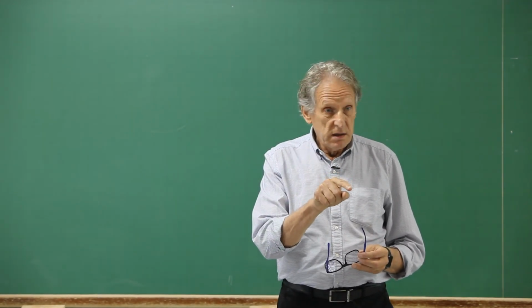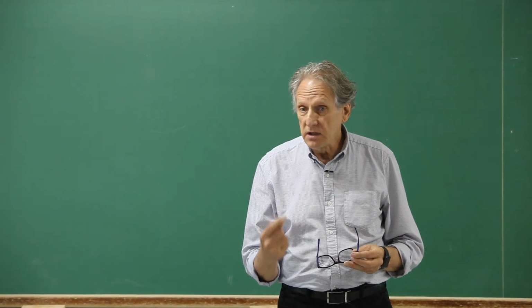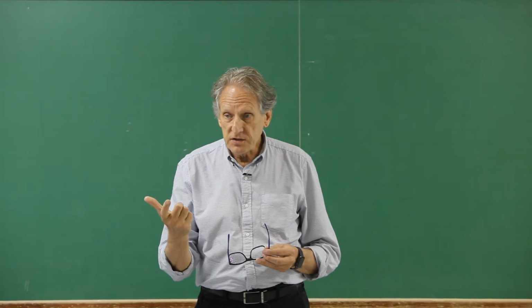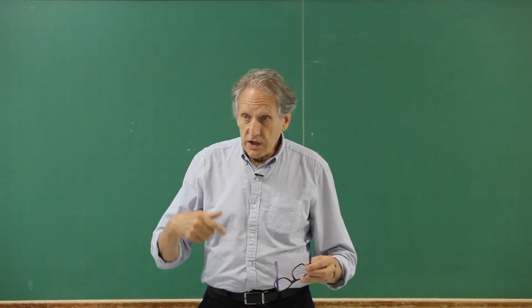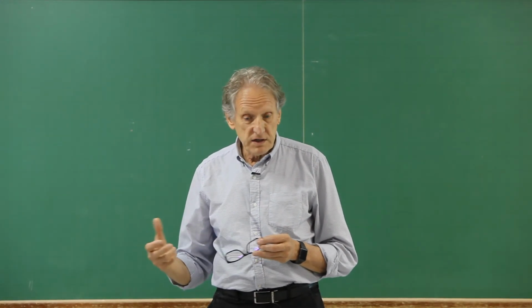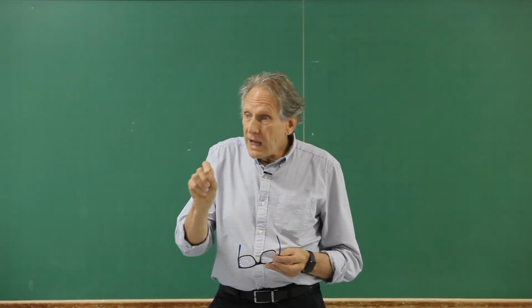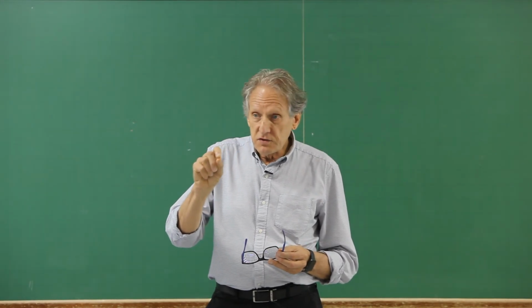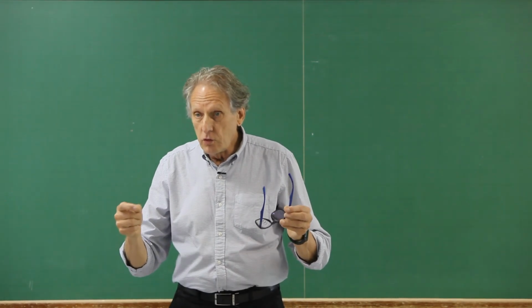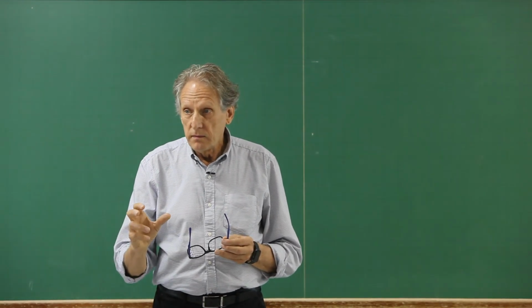You keep it there because time is the best relaxation parameter that you have in your equations, because time is related with the physics, and the way the equations are solved iteratively has a lot to do with the physics, the way the variable changes. And you can tune up the time in order to have small time steps, so you are driving your solution smoothly and slowly, so more stable.